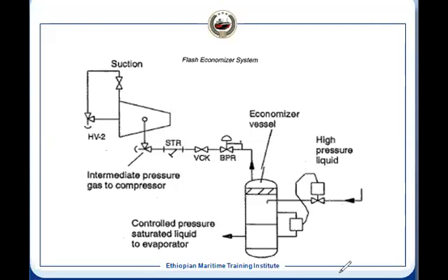And what is happening here? In that case, a heat transfer will take place. It means the high pressure liquid is coming, and this is in a liquid state. So when it is passing through this, it's coming here. Then a level is maintained so that it is the liquid which is going to the separator, not the gases.